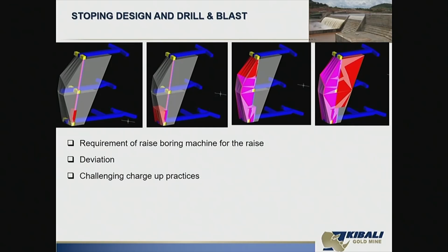But in this specific rock also, we have some issue, based on various core logging. We have seen that we have an issue with our foliation. From experience really, if you look at any of the exploration holes or any production drilling holes, the hole always tends to deviate after 10, 15 meters exactly in the same direction. Imagine when you increase the level spacing, so what do you end up having? Deviation is a challenge when you have to increase the sublevel spacing.